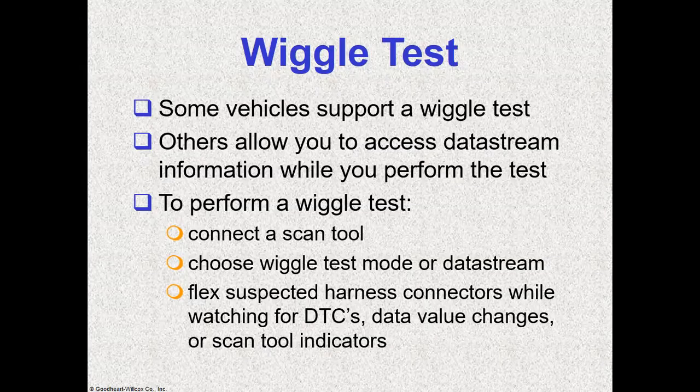If we have a cam sensor, crank sensor, temp sensor, and other sensors running through a loom, and any one has a poor electrical connection, the wiggle test can bring it up, but chances are the part of the wire where we wiggled probably has the issue. We then have to comb through the harness, which can be a headache depending on where the break is.